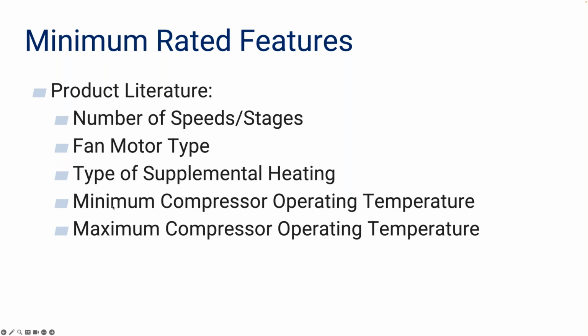One of the things that came up in comments already is that for dual fuel heat pumps, this should be a lot higher. So we're going to propose something around 25 degrees for dual fuel heat pumps, and that's where the compressor shuts off, and at any temperature below that, the furnace will kick in.